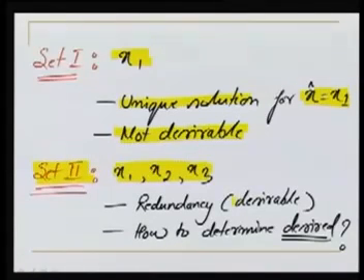Now this is very much desirable, because if in x3 there is some error, the chances are in x1 and x2 the error will be less. The errors are always there, but we have a way to check for huge amounts of errors, as well as we are carrying out multiple observations, so that we have more sets of data. The redundancy is there, and this redundancy is very much desirable whenever we do surveying or any observation.